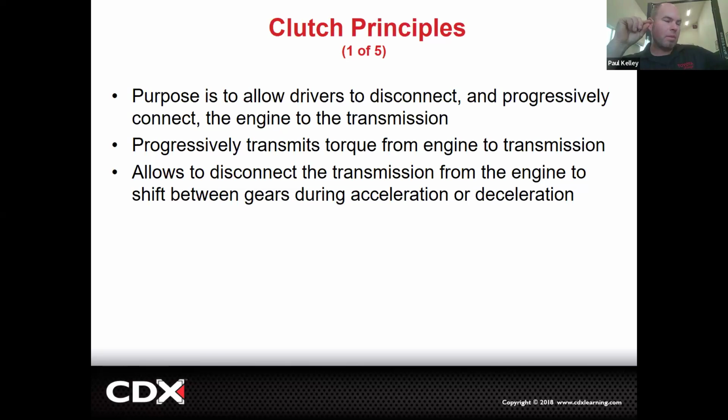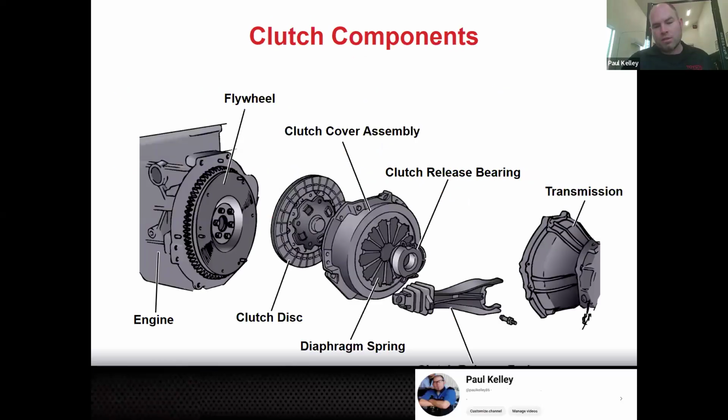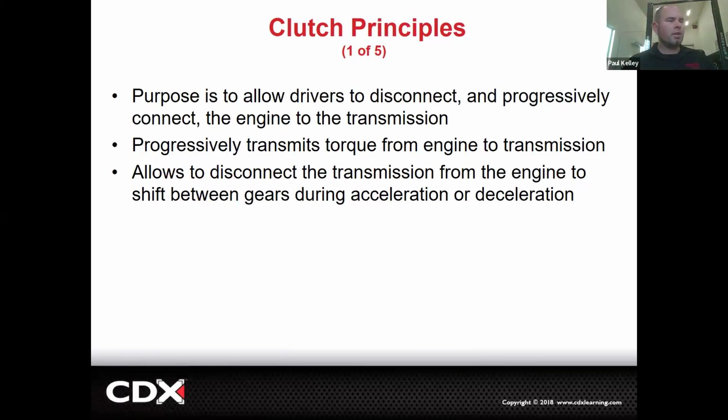I just about guarantee you, I bet you 9 out of 10 times, maybe more, when the customer says they engage the clutch, what they mean is when they engage the clutch pedal. When you push the clutch pedal down, that's disengaging the clutch. The clutch was shown on this page, right? By default, that disc is squeezed by the pressure plate. Boom. If you don't touch the pedal, I promise you that clutch is engaged. If you push your pedal down, now that clutch is disengaged. Right? So some of it's just terminology here.